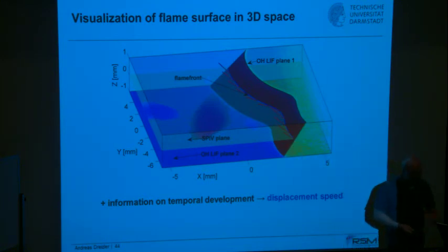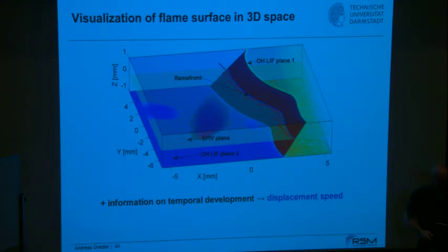Why? Because if you would take it even with solid seeding particles at the flame front, you would have already density effects. And this definition I've shown is valid only for the fluid with the density of the unburned. And that means you have to take it slightly half a millimeter or so displaced from that flame front.